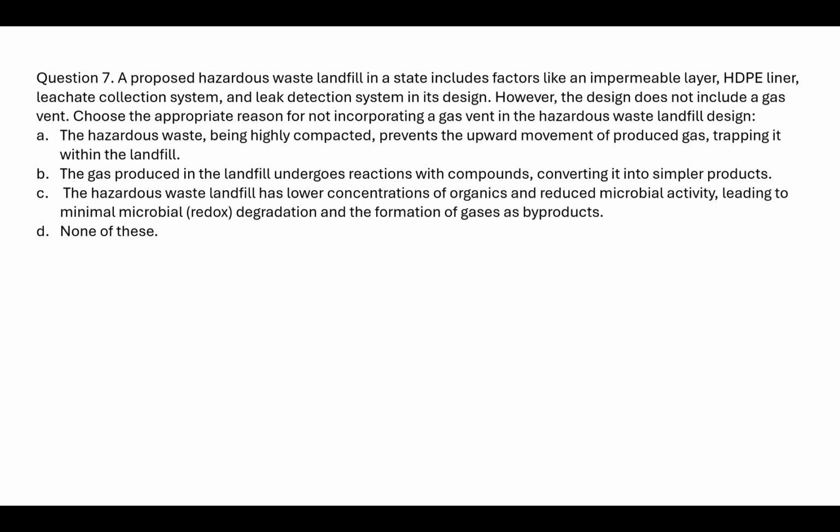If the food waste and the tree cuttings are not sorted, they go into the municipal landfill. Then they have a very high concentration of organics, and these organics are carbon which serve as a source of food for the microbes, and microbes feed on them, and because of absence of oxygen in the landfill, anaerobic degradation takes place, and methane, CO2, and other gases are formed.